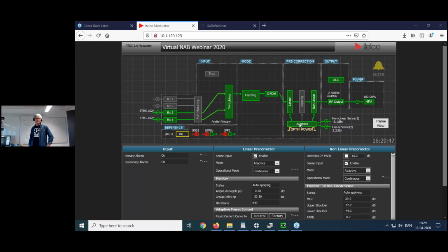Then you have to switch your amplifier to a more linear operational mode, and that certainly costs efficiency. And this is where mathematical schemes like these set in and can still save us energy and cost by extracting linearity out of a transmitter which is actually not very linear.